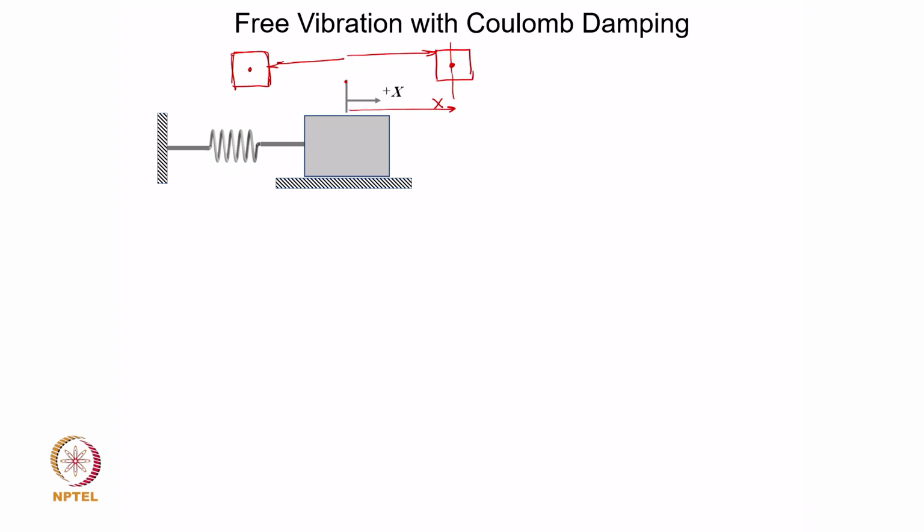And after that, once the velocity comes to 0, kinetic energy will be 0, the strain energy in the spring will reach its maximum value, and the compressed spring will now try to push it back again to its equilibrium position. This is how, just like our pendulum case, the body keeps on swinging around the mean equilibrium position. So, x equal to 0 at this point, and we are looking at the motion starting from t equal to 0 at this rightmost extreme position.